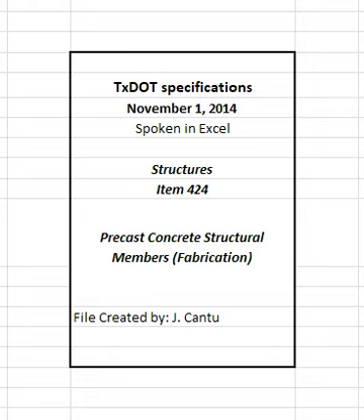Revise the concrete placement and consolidation procedures, and review the concrete mix design and batching procedures, if necessary, when unacceptable defects such as excessive honeycombing, aggregate or mortar pockets, or surface air voids, bug holes, are present. Provide supplemental vibrators or modify the vibration system when required to accomplish thorough consolidation of the concrete and complete embedment of the strands, reinforcing steel, embedments, or ducts. Avoid segregation or excessive bleeding of the concrete during vibration.